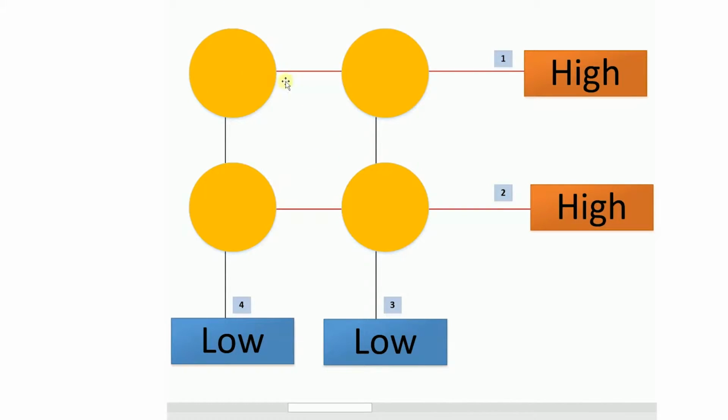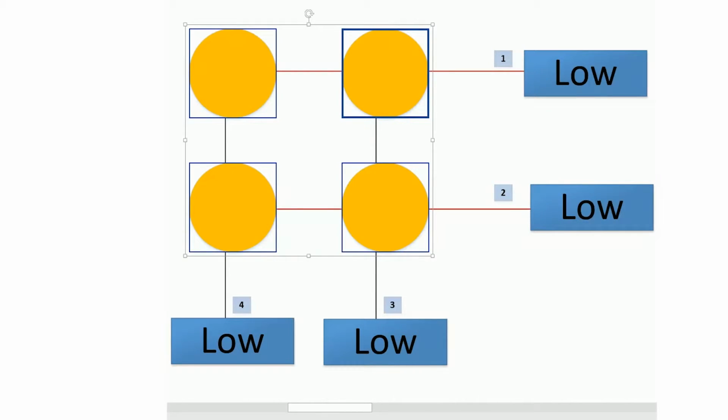There is a way around this. In order to get the 3 LEDs, the top right, the bottom right, and the bottom left on, with the top left off, we use something called multiplexing. Basically, we only turn on one column at a time, or one row at a time, whatever way you want to do it. So before I do anything, I'm going to set the rows to low, so that way nothing can be on. All these LEDs are now off.